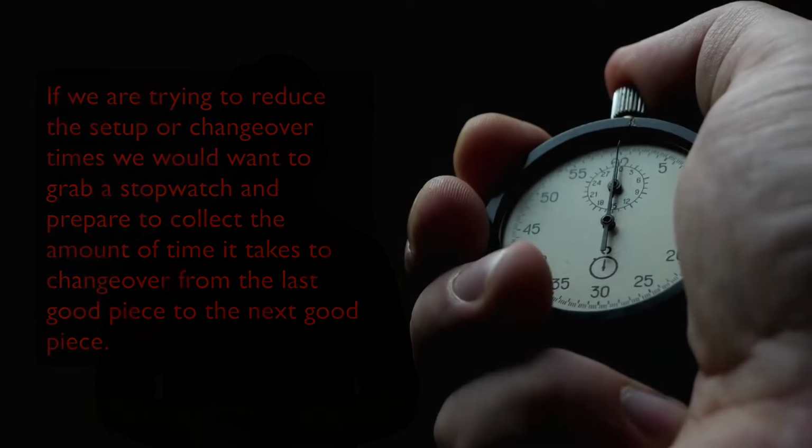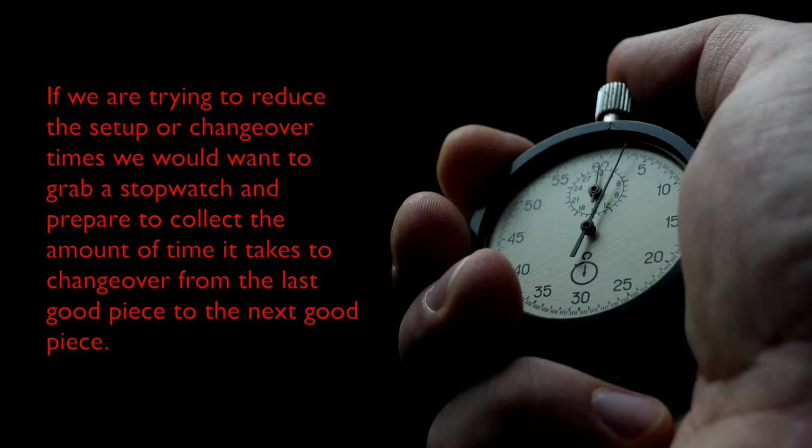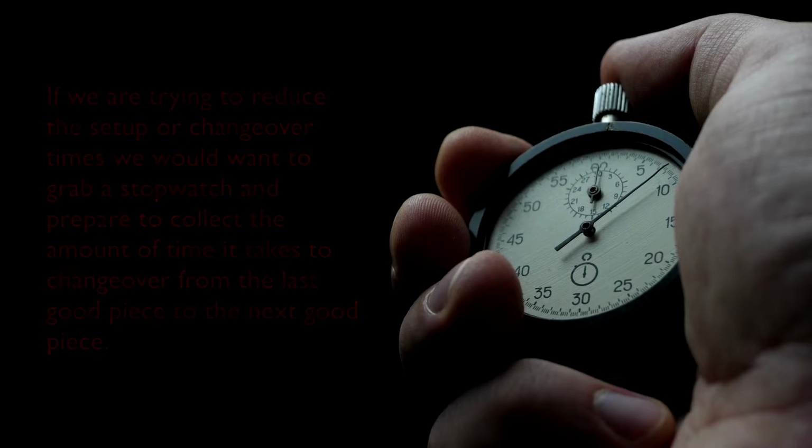In the first phase of the reduce methodology, your focus is on deciding what data to collect. This data should help you prove your improvements and continue to improve the process as time goes on. It is suggested that along with data, you decide what types of notes you want to collect while visiting the Gemba. For example, if we are trying to reduce the setup or changeover times, we would want to grab a stopwatch and prepare to collect the amount of time it takes to change over from the last good piece to the next good piece. This data would be documented.